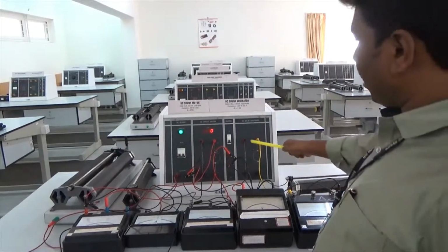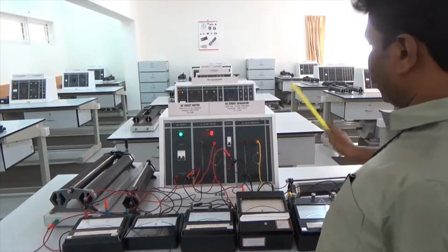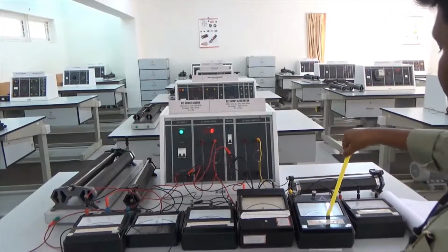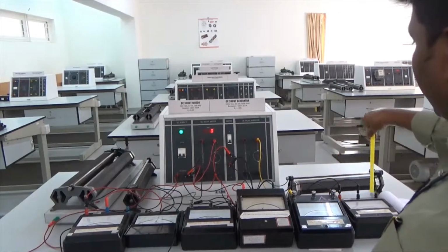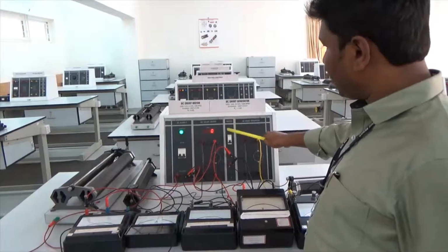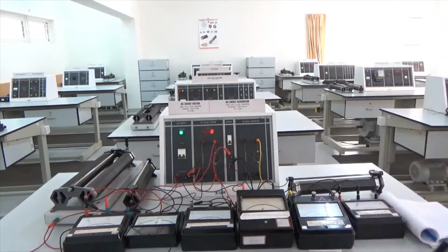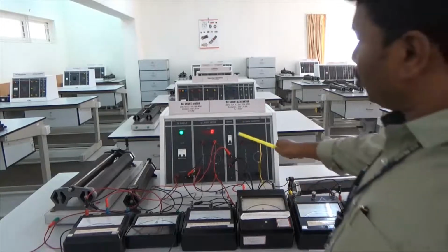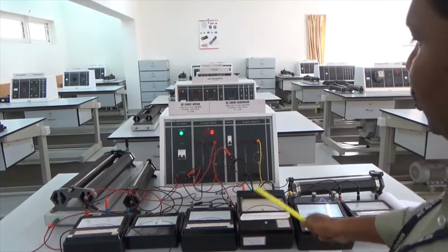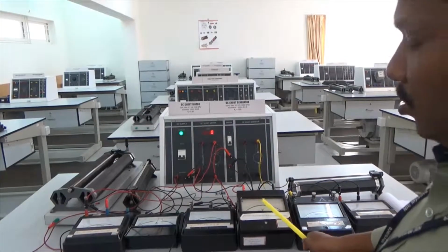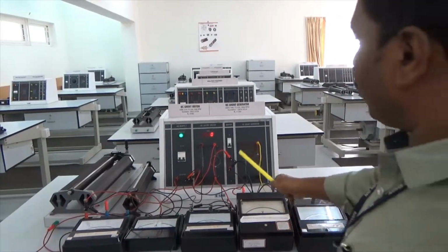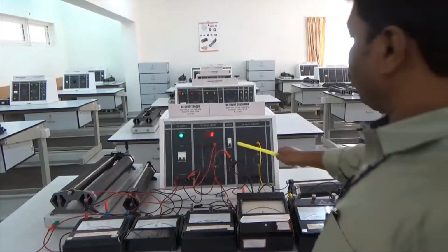So the generator circuit has a field rheostat here, which is in the cut-in position, and the armature terminals have the meters connected to measure the armature current and armature voltage. One more interesting thing is that there is a switch between the motor circuit and the generator circuit. This switch should initially be off, and it should be switched on only when the voltage across the two circuits is 0. That is ensured by this meter. Basically, this meter should reach 0 when you want to switch on the two circuits through switch A here.